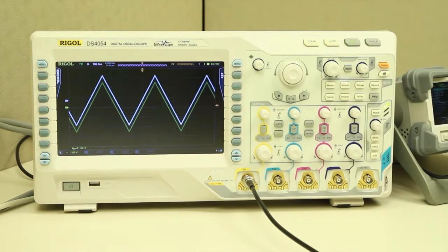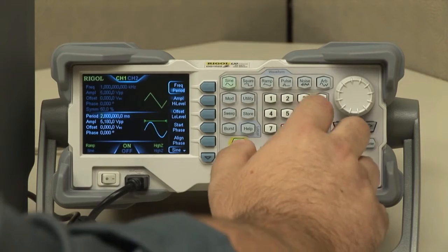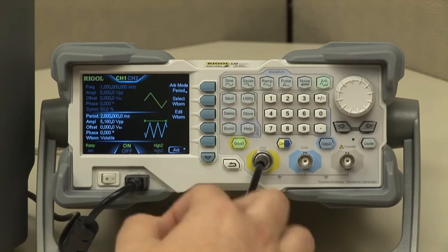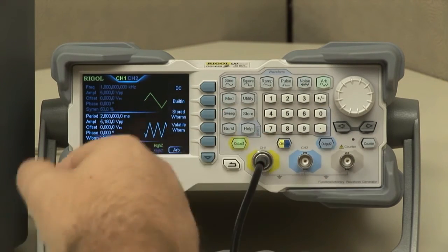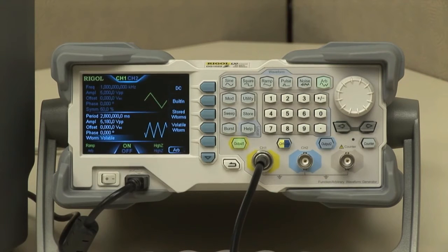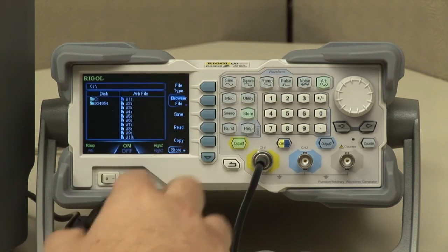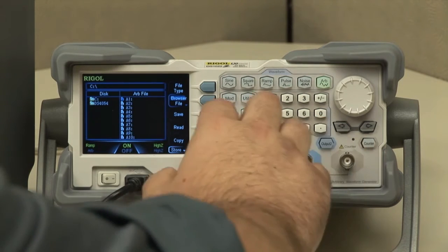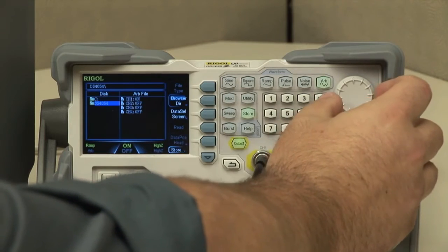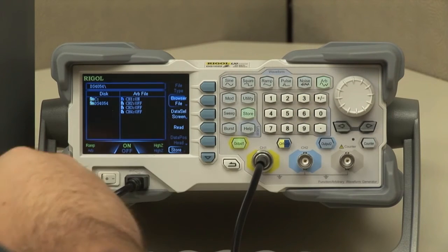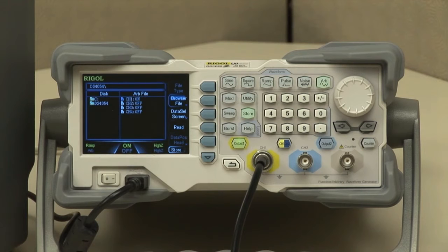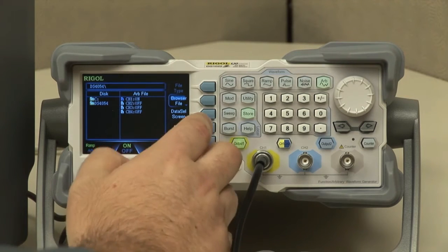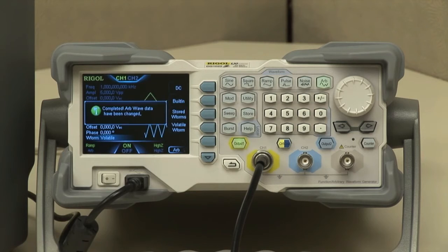Now that's saved, I'm going to transition over to channel 2, where I'm going to go into the arbitrary functions and then into select waveform. In here I can choose build function or stored function. For this I'm going with stored function. The build function has all our extra functions built in. Now that I'm in the stored function, I'm going to go over to our directory and choose our DS4000 oscilloscope. Then in File, I can choose between channel 1, 2, 3, or 4 for this model. I'm going to go ahead and read the information over.